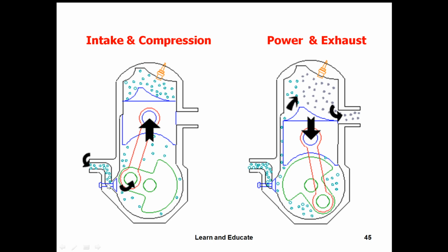This intake port will be allowing, that is, the pressure here will be reduced. As a result of that, automatically the fresh charge will be entering the crankcase. Then the further motion of the piston upwards will open this transfer port. Here you can see the transfer port.